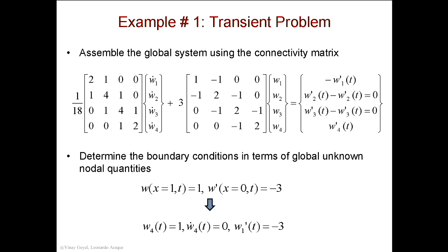You have to understand the problem, and this is one of the most critical parts in a dynamic problem: defining the boundary conditions. Many of the issues I see in dynamic problems, where results don't make any sense, have to do with the initial boundary conditions. That's usually where I see the problems; the initial boundary conditions don't make sense.